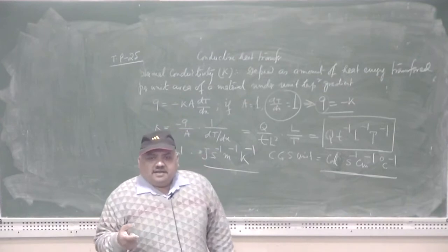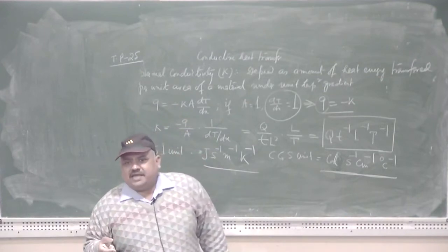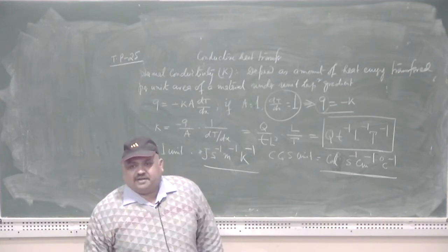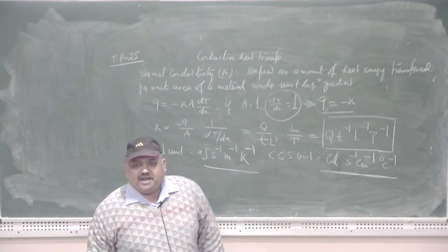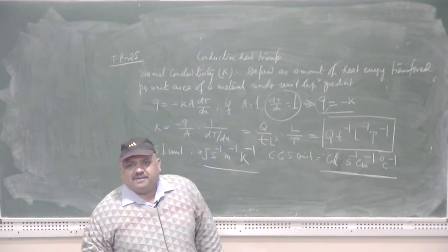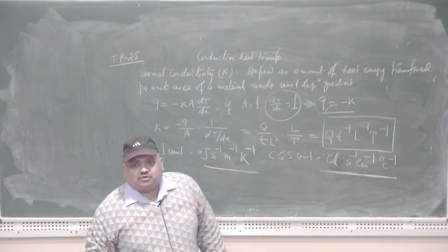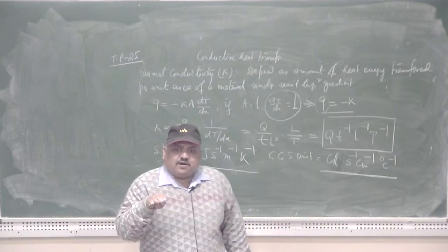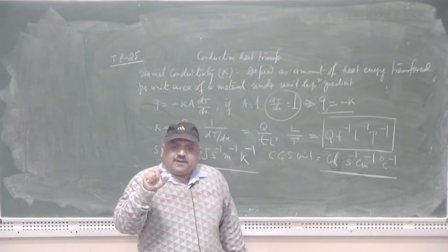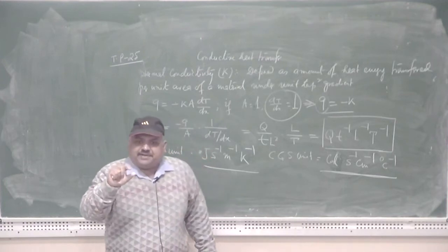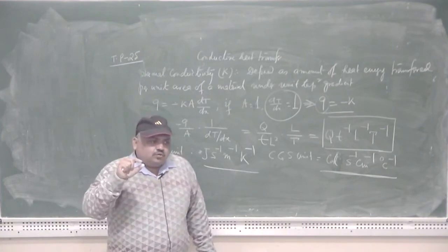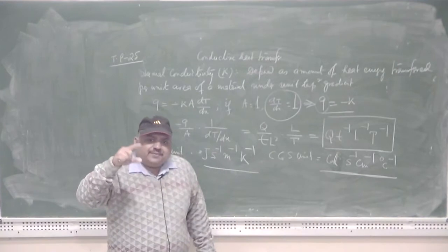And also, on the other hand, you can tailor the mechanical property as well as the macrostructure of the material you are going to solidify by having a proper choice of the mold material, and by having a proper choice of the superheat given to the liquid metal in order to get it melted. And how can the superheat be defined? The superheat is defined as the margin of temperature through which you have increased the temperature during the course of melting.